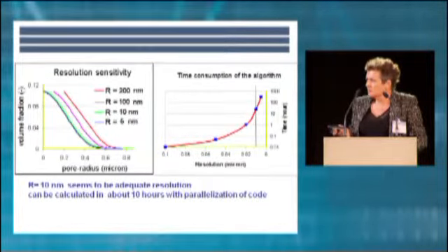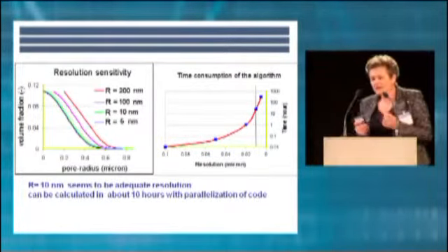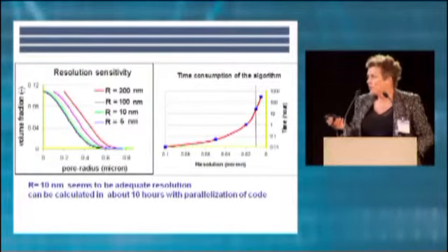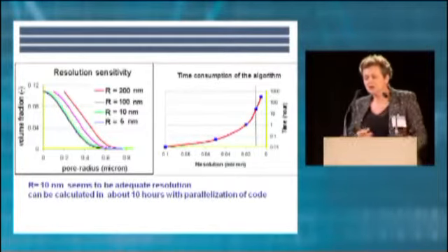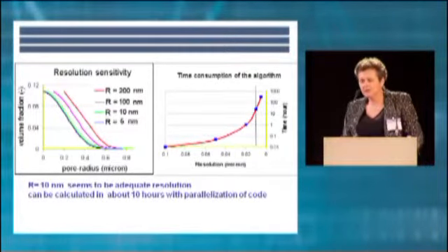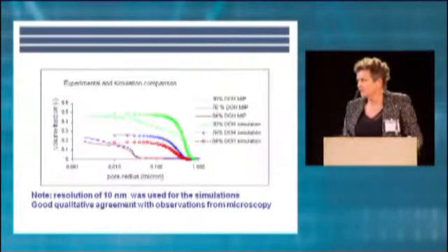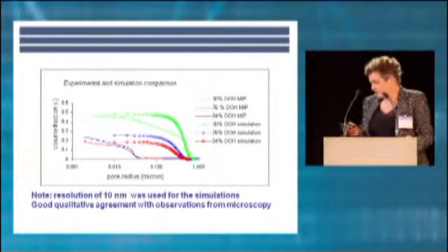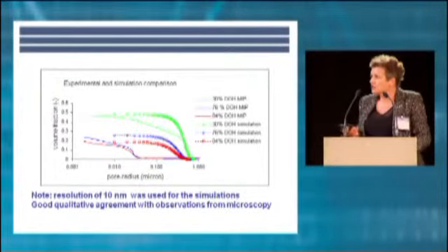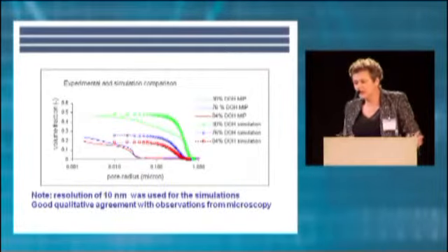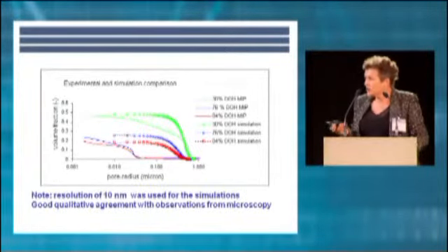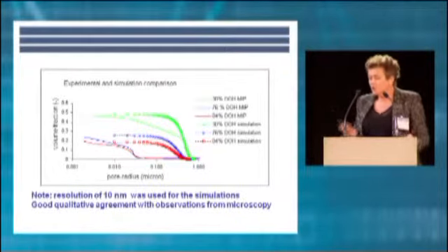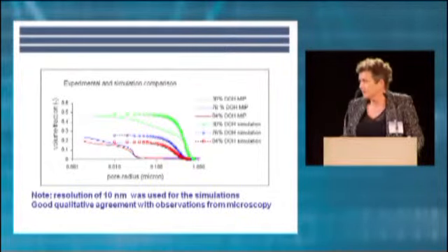With our latest advances, we can now model those pores down to a 5 nanometer size, which is starting to be the level that we need to get to really understand the properties. And of course, we can show that conventional methods for measuring pore size, like mercury intrusion porosimetry, because they're actually looking at pore opening, do not well capture the pore size.